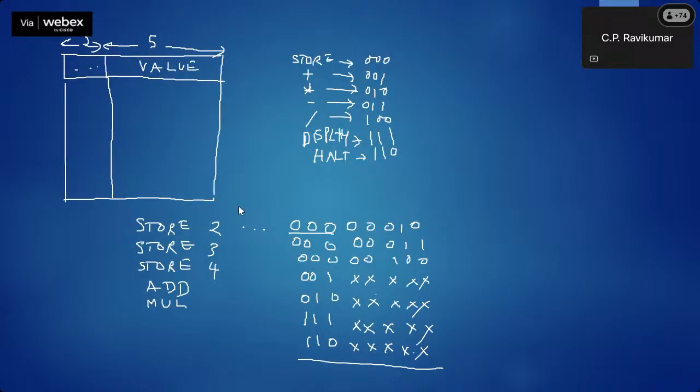So we have a memory that will store this program. Okay? So your processor or calculator must start reading this content and look at what these 3 bits are. If it is a store, it should take these 5 bits and store it on a stack. And then, the same thing for these 2. When it comes across an add instruction, it should remove 2 elements from the stack, add and put it back, and so on, right? So it should execute these instructions.